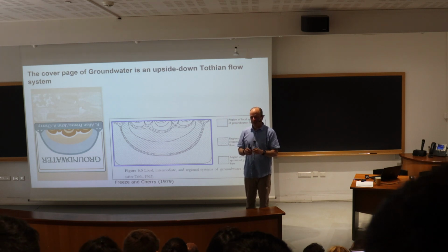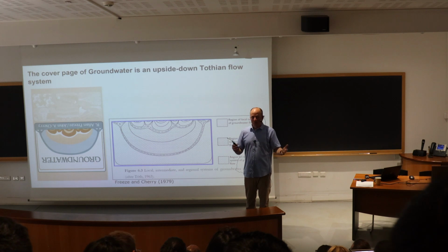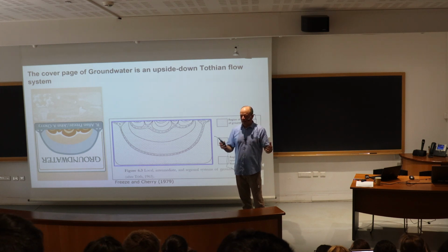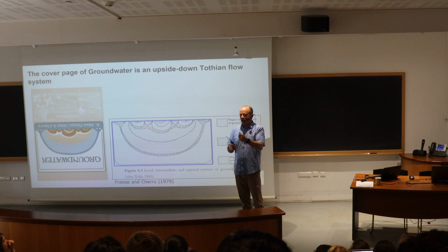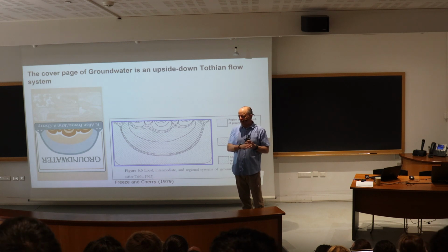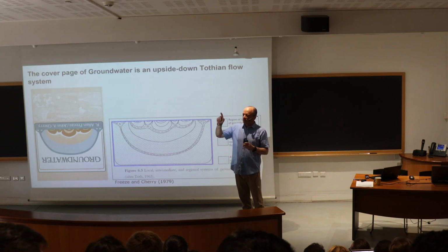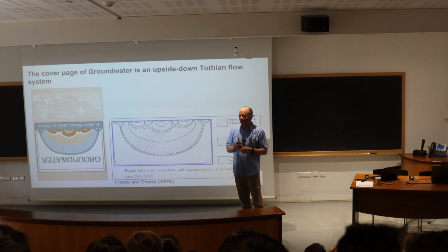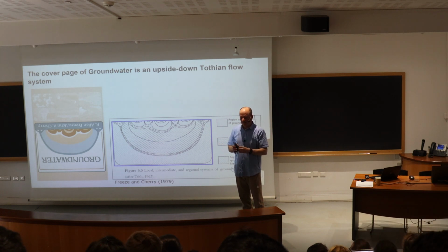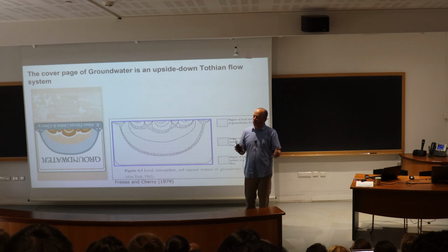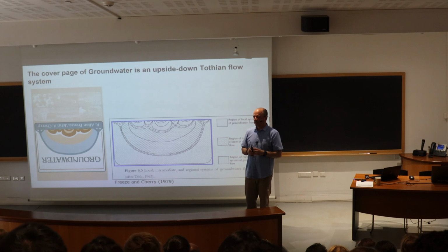You would use very small scale, but what happens is that often you don't have that luxury of having a very small scale description of hydraulic conductivity, so you use some equivalent hydraulic conductivity, and then you have to jack up dispersivity because the average velocity you get from your homogenization, the fluctuations around that average will be huge, which you represent with dispersivity. And again, it's like Danny mentioned, you're looking at another process where the REV for flow might be okay, but for transport, you might be off.